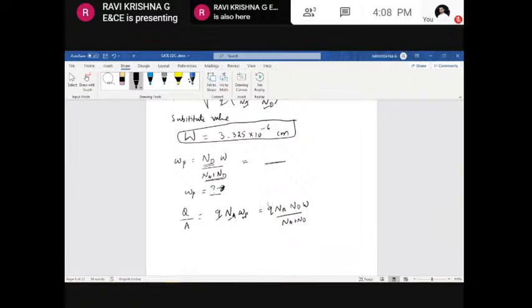Because here we know the charge, the value of this charge, we know the concentration of the acceptor atoms and the donor atoms, and we know the total depletion width. So from this, what we will get here is the total charge per unit area will be equal to 4.836 nanocoulomb per centimeter square.